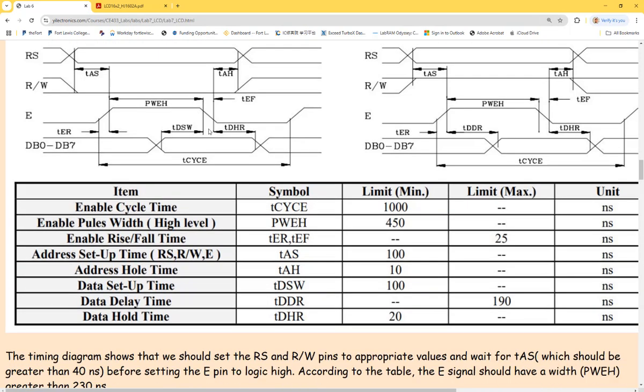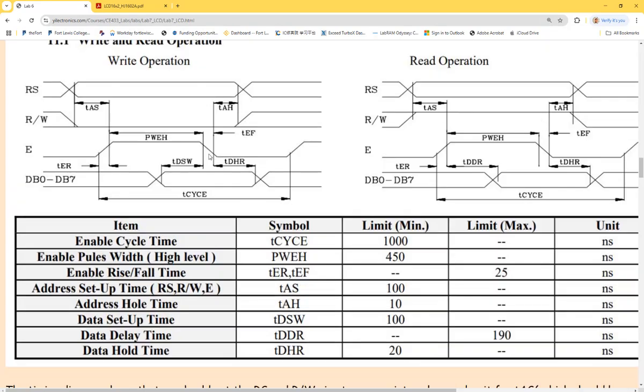Okay, and it requires the enable pin to be put down, so it has to be up first and then put down to enable the write. So that's the only critical thing you need to be aware of. I'm going to show you the details of the code on Thursday and give you probably the template to look at and print out. But keep in mind, you need to put the enable pin down to ground from logic 1 in order to start writing.